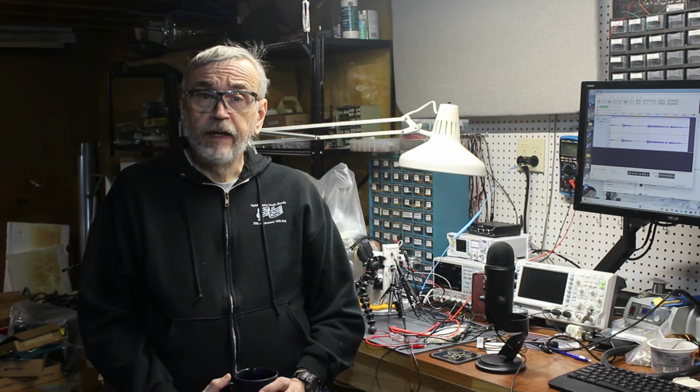What might such a thing be good for? Maybe you'd want to measure whether you're delivering enough light to cure UV-sensitive epoxy. Add an integrator and a comparator to our photometer, and you have the basic circuit. Or perhaps you want to build the receiver for a remote control. That would need some sort of photometer at the front end. I bet you could monitor the concentration of some colored chemical in solution. I'll let you think of other things you could use a photometer for. I've got a couple of fun ideas, but they'll have to wait for another video.